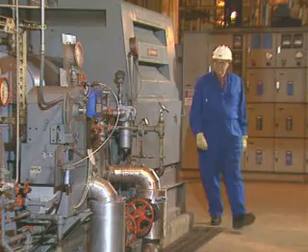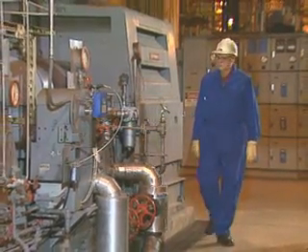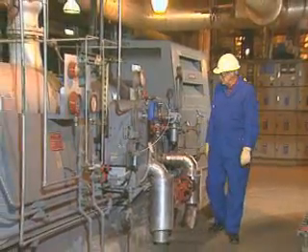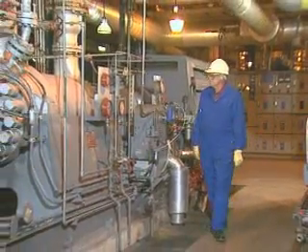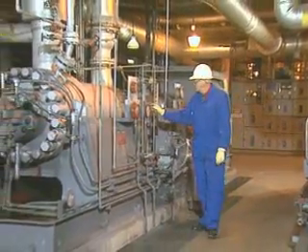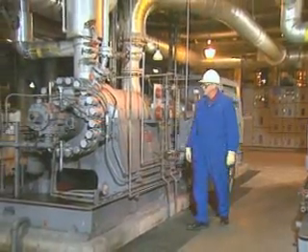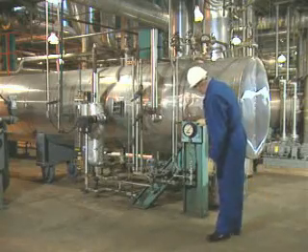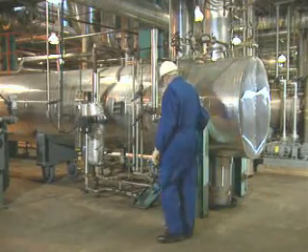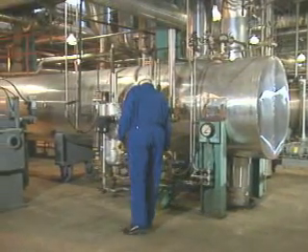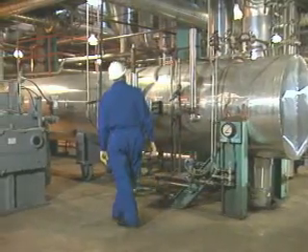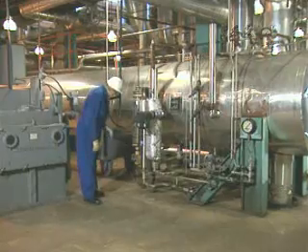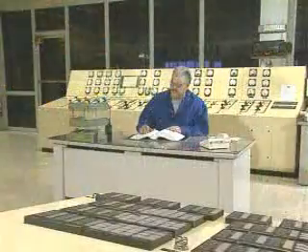If you're responsible for keeping a condensate and feedwater system running smoothly, you must be thoroughly familiar with normal operating conditions for the system so you can distinguish between usual and unusual conditions. Making regular checks of levels, temperatures, pressures, flows, and valve positions throughout the system as it operates helps you detect problems early so that major trouble and costly downtime can be prevented.